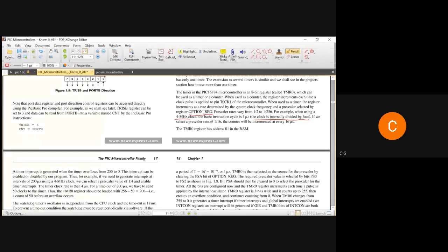And then when we set a prescaler like this, people may tell that this answer is wrong. Why? Because this is not given to us. The 4 megahertz clock pulse is given. Then the main clock is dividing it by 4, so it is a mod 4 counter. When 4 clock pulses of 0.25 microsecond come, it converts them into 1 clock pulse.